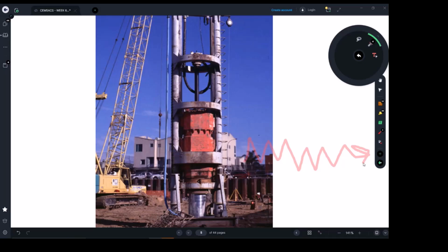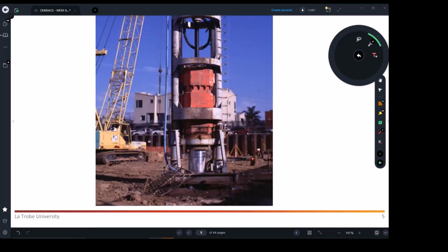Then the engineer will be measuring what's happening with the pile. There are some sensors that will be connected to the pile which you've already built. So this is the pile, it's already in the ground. And what you're going to do is connect that pile to this dynamic, what we call a vibration generator. So this is a vibration generator which will be attached to the pile. Then this system will be providing kind of harmonic motion, something like this, right? It's a sine curve. That generator will be applying a motion like that.